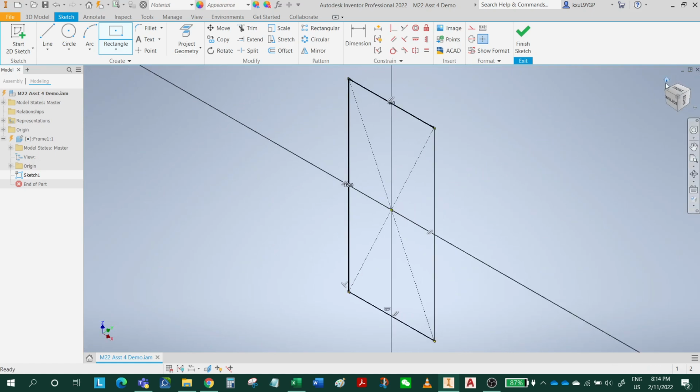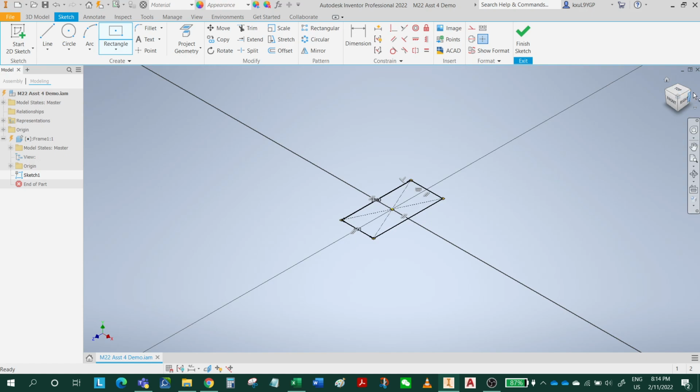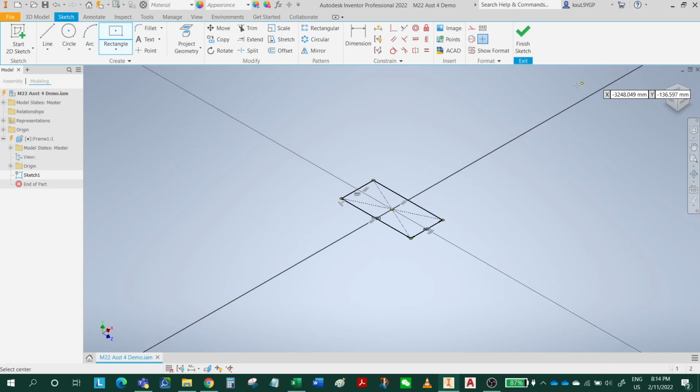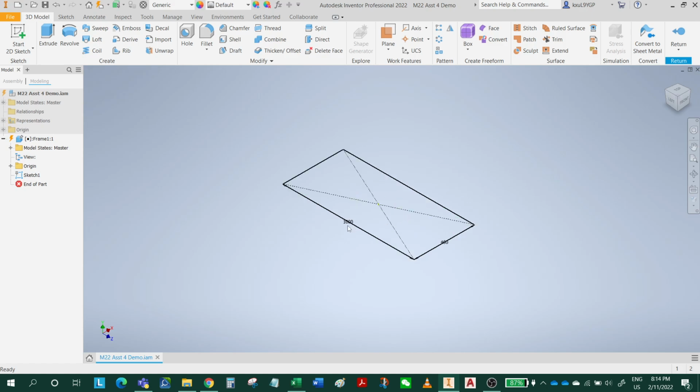Goes isometric. So you see this isometric actually is not exactly what I like to see. So I want to have this as my home isometric view front. So I'm gonna use this one. Okay, so I'm gonna set this as the set current view. Oh, it's in the sketch mode. So I'm gonna click finish sketch. I'm gonna set this as the home view, right? Fixed view. Then I'm gonna edit sketch. So yeah, I finished my sketch.